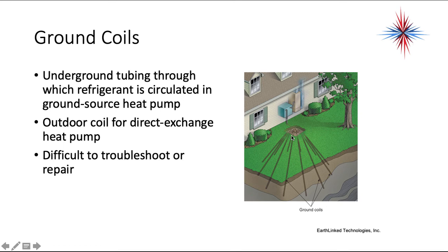Okay, and when you put copper or brass, usually copper, in contact with the ground, you have electrolytic action that occurs and it will start to corrode. These coils that are buried in direct contact with the ground do not have a high lifespan. Additionally, you have to know exactly where these coils are, and when houses change ownerships, sometimes people build new things on the property and can actually break these coils.